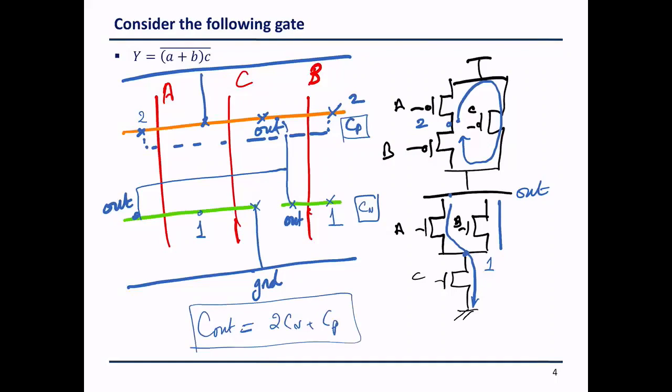Okay, so also I have two diffusions and I need the spacing between them, because I did not make them touch each other, they are different nodes. So this means that I'm going to lose on area. Even this P is really distorted. It is not very compact if you want to draw a regular layout. Okay, so you see the difference when we pick the wrong Euler path, what happens? I cannot push this onto this because these are different nodes.